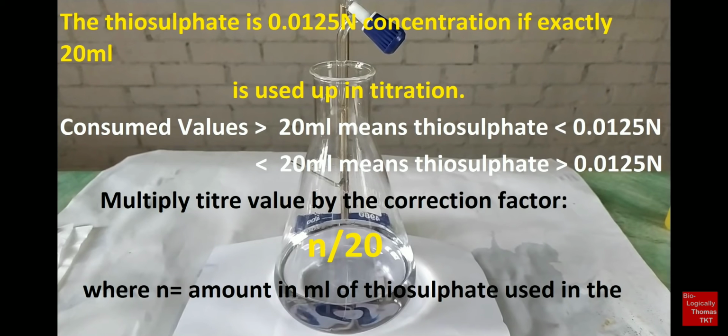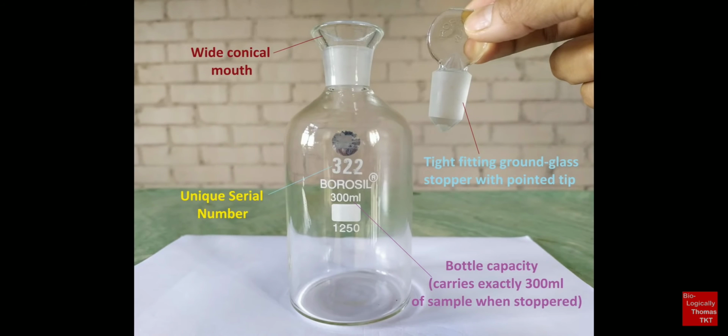Once the sodium thiosulfate has been standardized, we can proceed with the DO estimation of the water sample. We begin this by first collecting the water sample from the source using a special container called the BOD bottle. Each bottle has a unique serial number printed on the bottle in order to avoid sample mix-up when collecting numerous samples from different sources. Details on the sample may be entered against the same serial number in a collection registry book in the field.